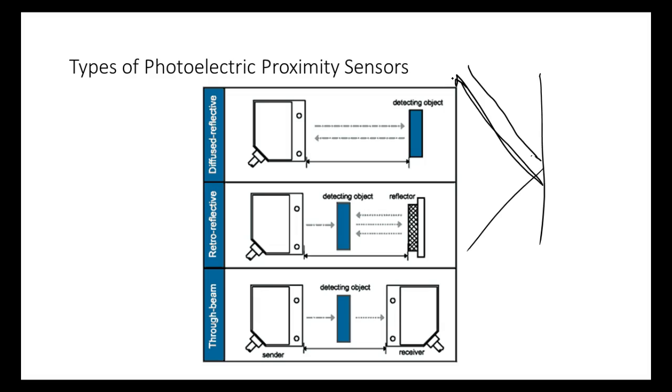Most of your taillights have retroreflectors in them, so they can see your stoplight even from an angle. Our lights are buried in a reflective surface, and they're back here. If I was over here, I couldn't see it, because the light's going out here, right? You understand that? So what do they put on here? They put a retroreflective lens. So the light is coming out here going off at an angle. So we use a retroreflective lens to spread the light over an angle, right?